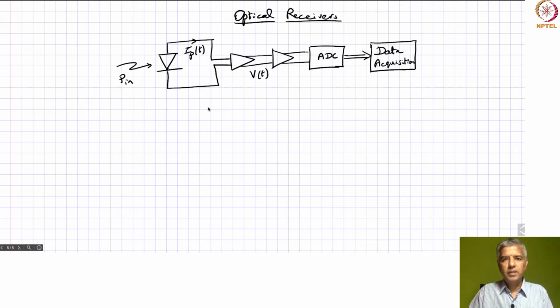So this is typically the optical receiver that needs to be designed for any sensor application. We looked at the example of a PIN photodiode, why we need that PIN structure, and then we started looking at some of its characteristics in terms of its responsivity as well as the response time, which can also be quantified in terms of the bandwidth of the overall receiver.